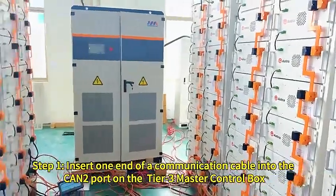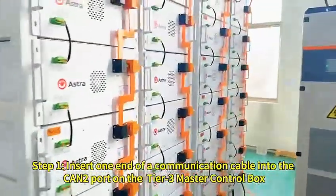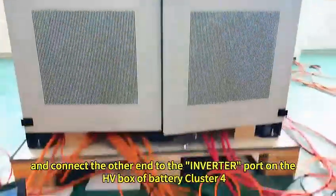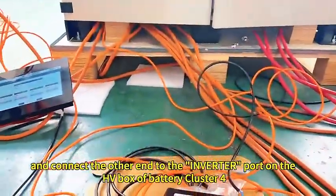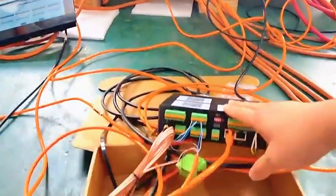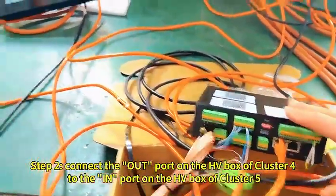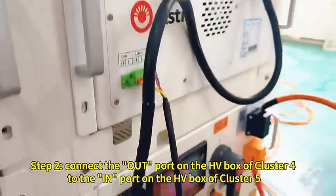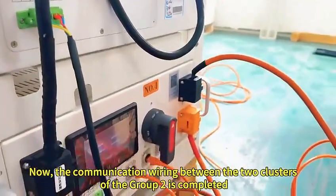Next, let's begin the communication wiring for the Group 2, which consists of 2 clusters labeled Cluster 4 and Cluster 5. Step 1. Insert one end of a communication cable into the CAN 2 port on the Tier 3 master control box and connect the other end to the inverter port on the high voltage box of battery cluster 4.